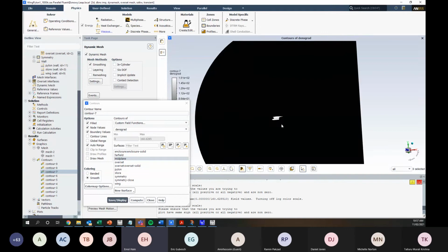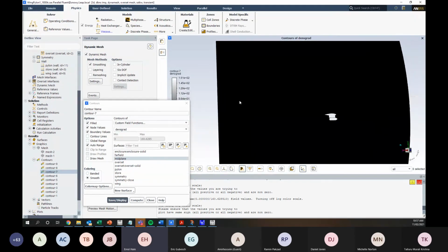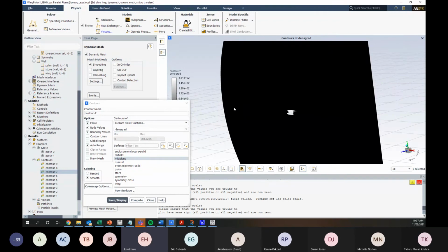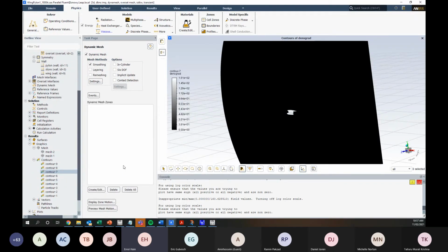Yeah, you're right. The symmetry plane is not 100% applicable for this case, unless there's another wing on the other side with exactly the same thing going on, not a fuselage body. But it's just the way that's been specified for the validation cases. So all the validation cases are done with the same boundary conditions, and that symmetry plane is used for all. And that's just to cut down on the computational expense.